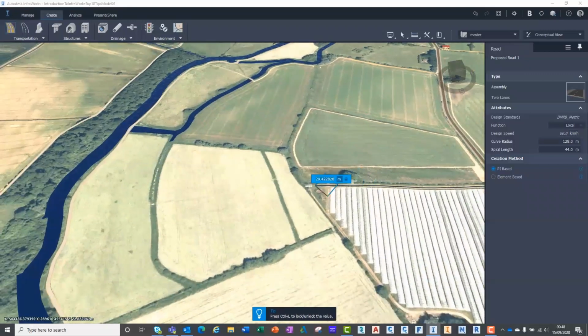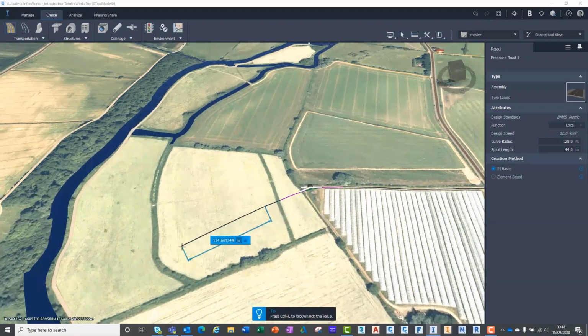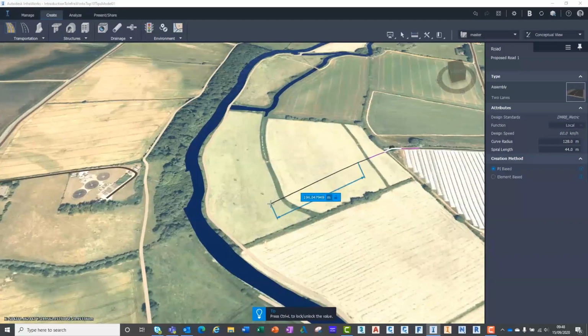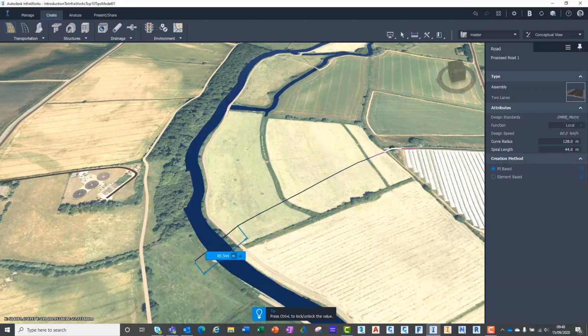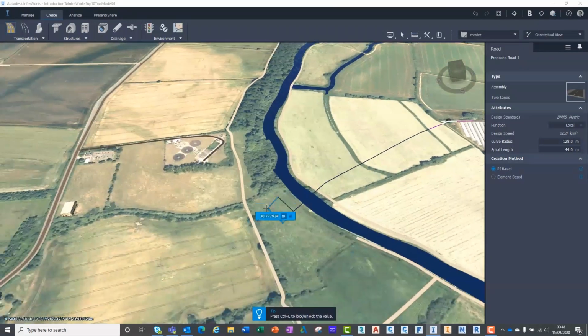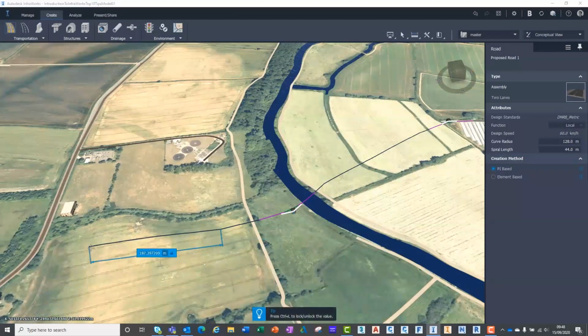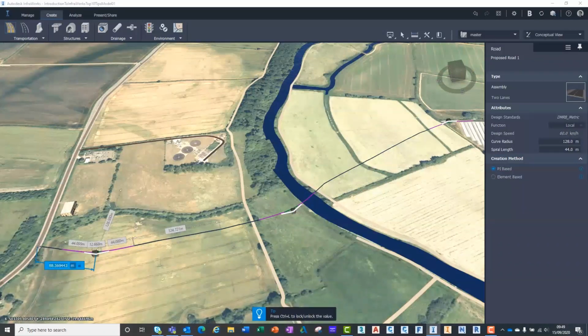All we do now is click the path for where we want the road to follow, like a polyline. You'll notice that the road alignment follows the contouring of the existing landscape. It will also add any radii required for corners and bends. When we reach a river or other water sources, simply continue using the component road tool. I'll show you what we can do with this later. Finally, InfraWorks lets us simply tie into an existing road. We complete the command by double-clicking with the left button of our mouse.